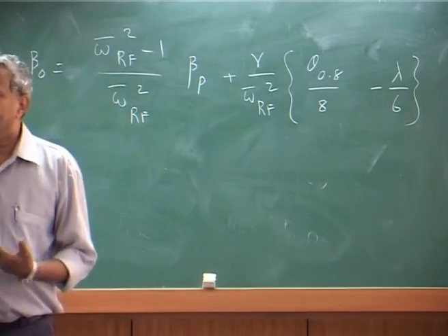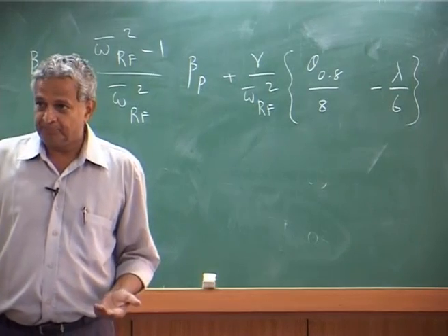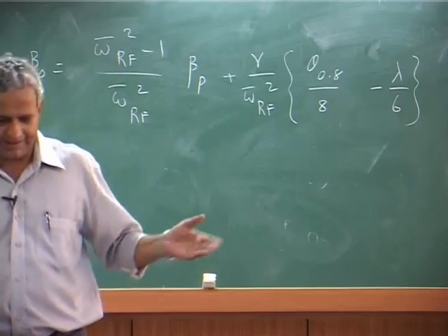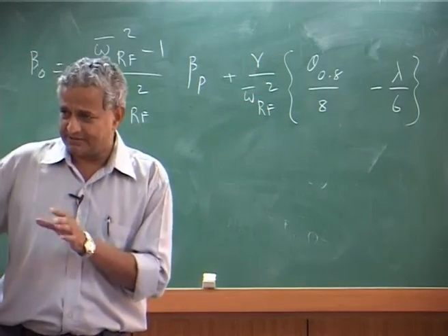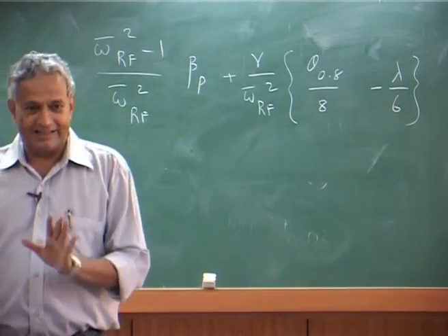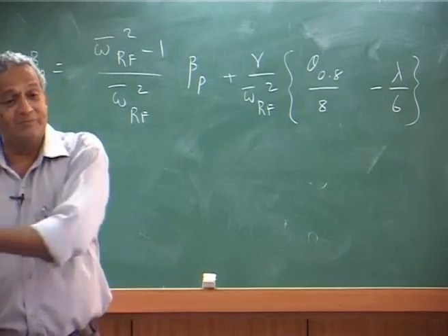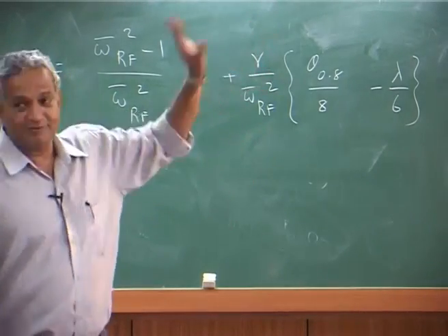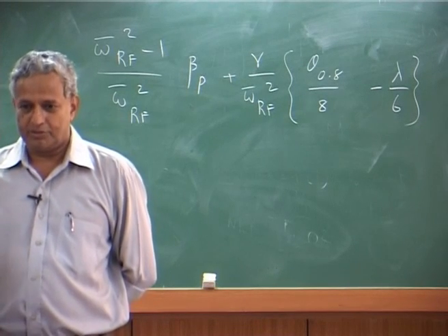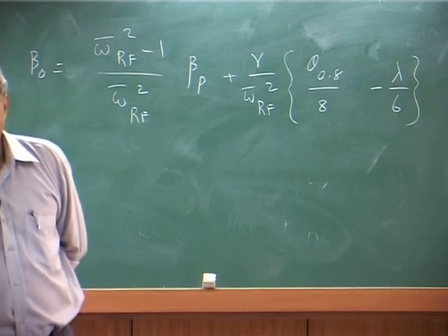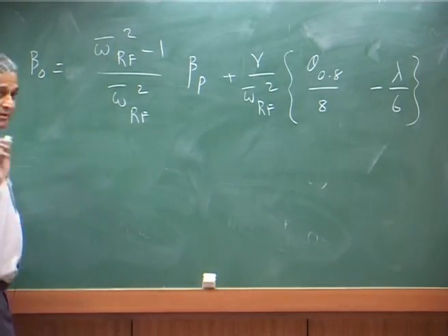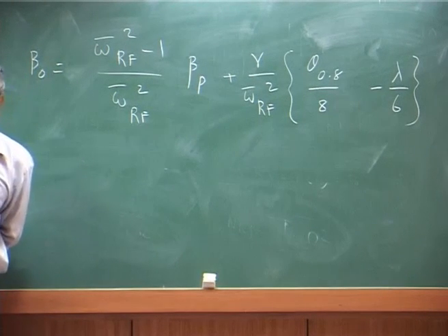Why do you want to have an ideal precone? Because usually all the blades are not hinged like this, they have a spring. Spring means it is again an idealization. Real blade will be different, but it can be made equivalent to this type of blade, because if I give you the rotating flap frequency of a blade, you can immediately find out what should be my k beta, if I know the mass of the blade.